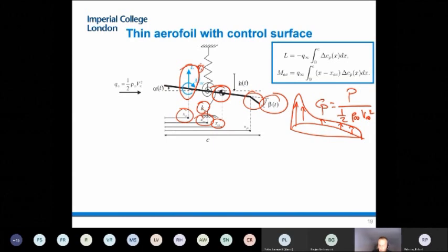And what this is saying is that I will have a distribution of pressures associated to the particular angle of attack and the flow conditions in which I am. I define delta as the pressure on the upper side minus the pressure on the lower side of the airfoil, which typically is what will happen. So you have another pressure field applied there, which will be pulling typically in that direction. Actually, they're both pulling in the right direction.